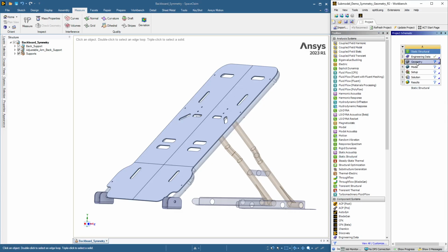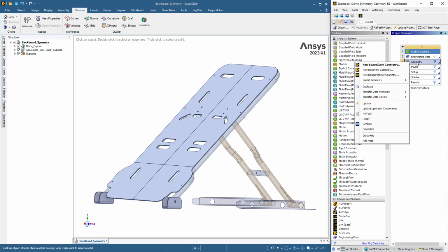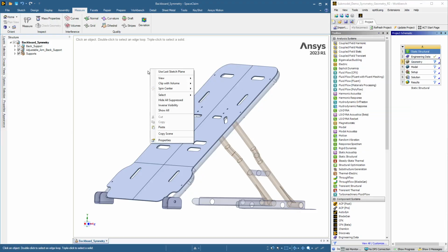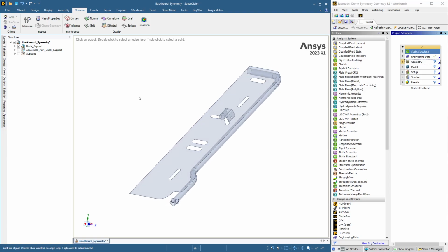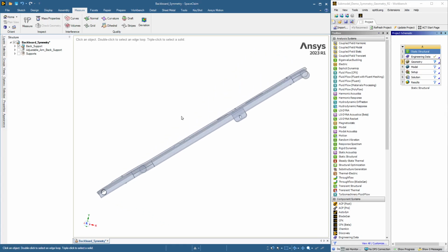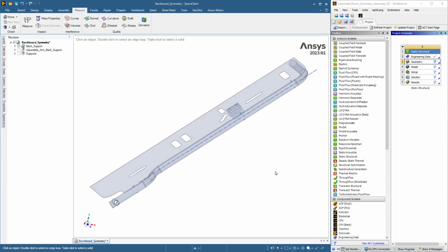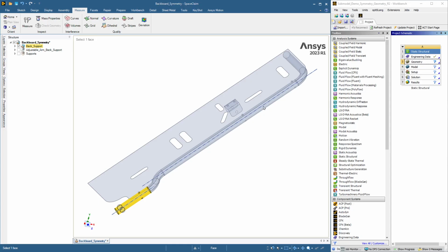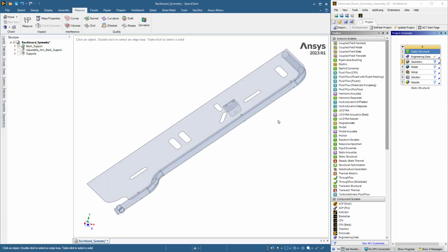The first part is a static structural for the system model. We're going to pull in the geometry that we see here, which I've already set as suppressed for half the geometry. We're going to simply speed up the demo by reducing the number of joints that have to be made. Then we'll go back and do a second video on the sub-model for details around the peak stress, which turned out to be on this hole.